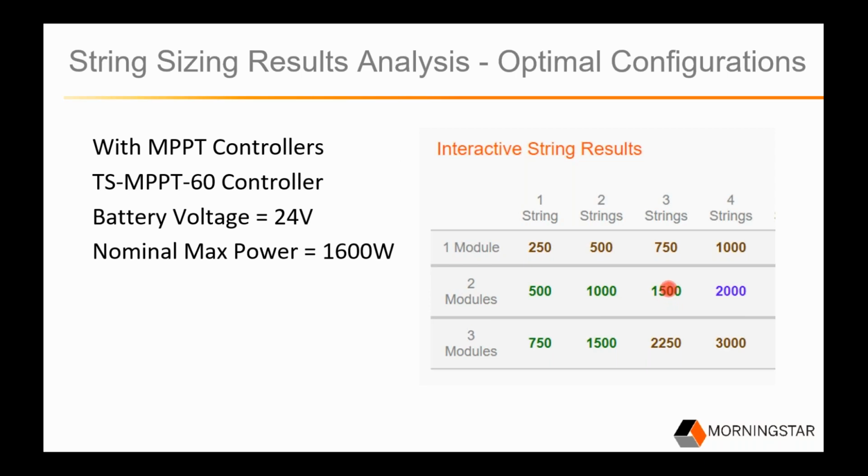For PWM controllers, the string calculator results will show acceptable sizing up to max power current that's less than the current rating of the controller. Array open circuit current should be less than the controller current rating. Maximum array current may be affected by location and tilt. Higher altitude, reflections, angle of incidence can all affect this.